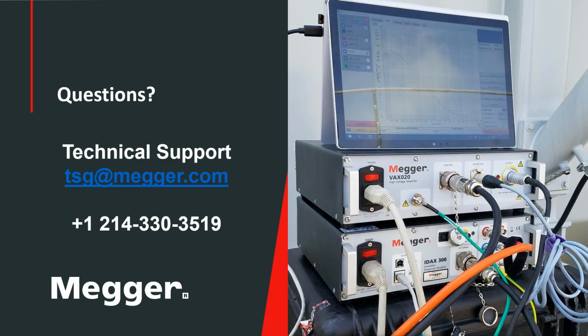I think there was one occasion when we were looking into one specific reference for different kinds of GSU transformers, and the only reference that we were able to find was in some specific literature for nuclear power plants. But besides that, the majority of the information is taken from the correlation of the limits on the liquid insulation with respect to the solid insulation.